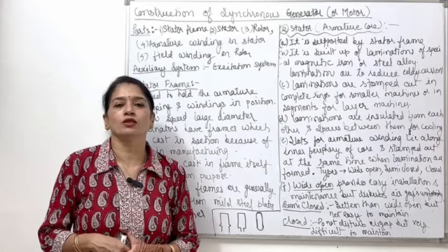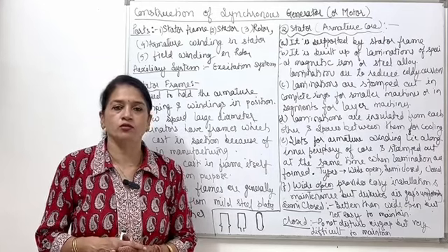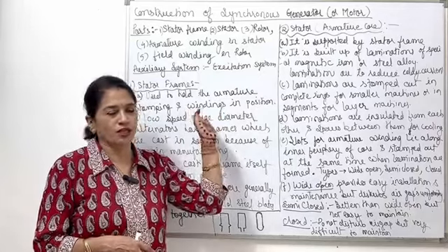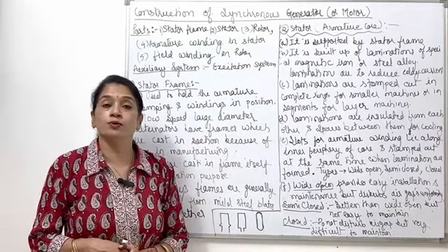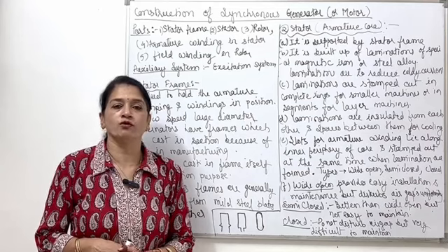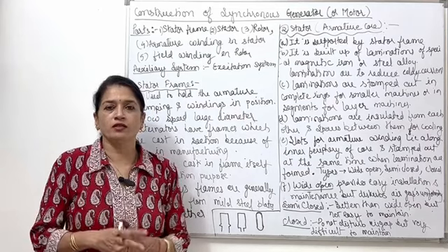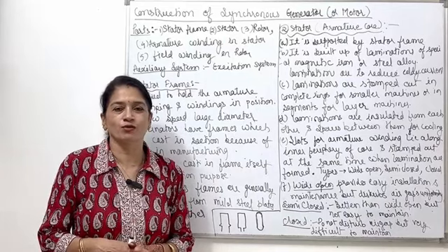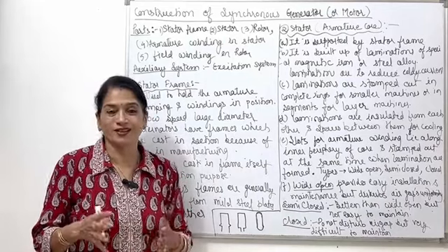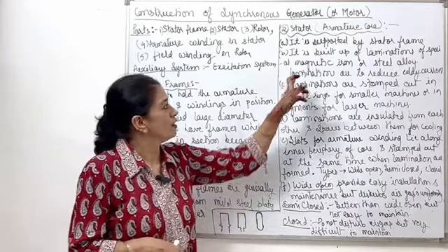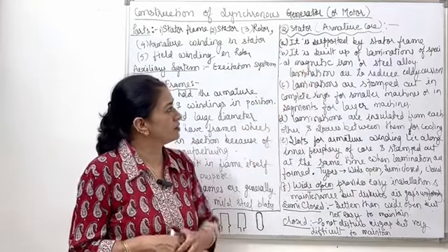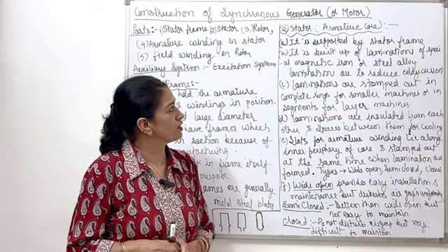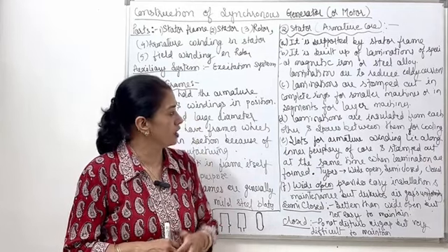The stator is nothing but the core of the armature winding, so it is also known as the armature core. It is supported by the stator frame, as I said earlier, and it is built up of laminations. Laminations are provided for avoiding eddy currents. I discussed eddy currents a lot in the single phase transformer videos, so please go through that, my Hindi version of the discussion there. These laminations are made of special magnetic iron material or steel alloy.